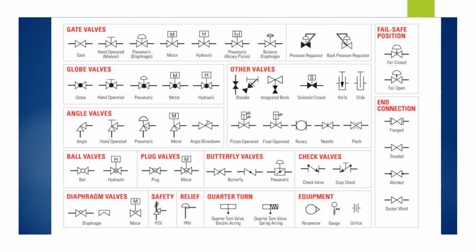Things like that. One major point of advice I have is that usually at the beginning of your printed-out P&ID book, or more commonly files on your computer, there's some kind of key similar to this, but a little more extensive, with all your different symbols that might be even more specific to your company. So it's good to find this and reference it as you read the P&IDs. And often you can find some symbols online too, since it's kind of standard throughout the industry, if questions come up.